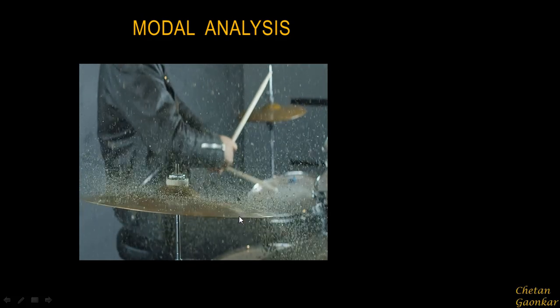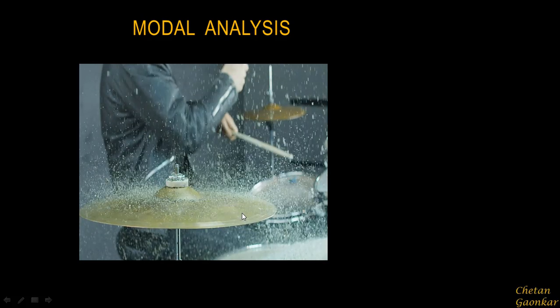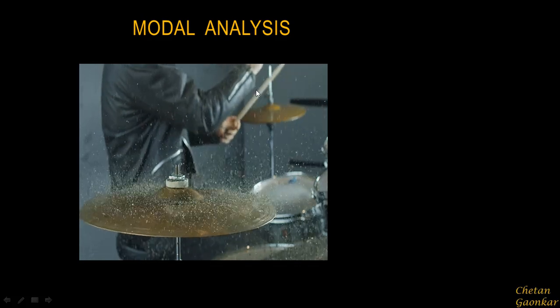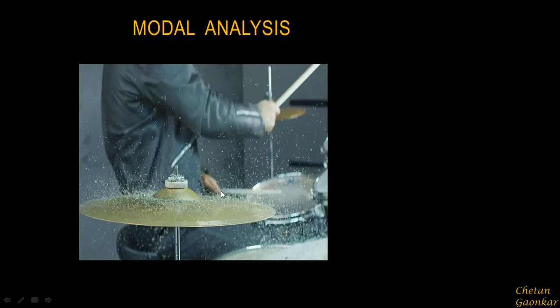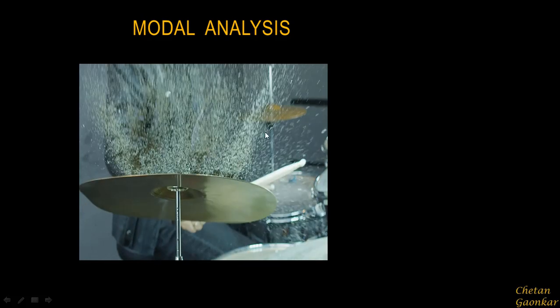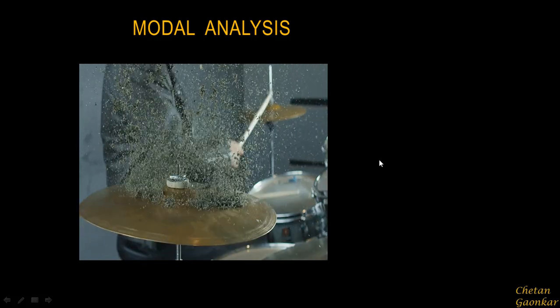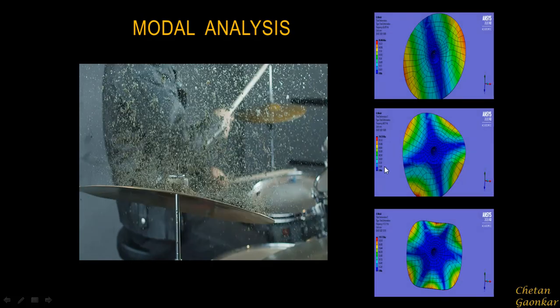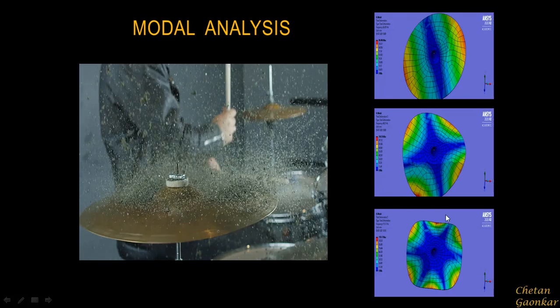Now basically the dynamic vibration behavior is nothing but, as we have discussed, the response of a structure under external excitation. Okay, so if somebody wants to understand the dynamic behavior of the structure for external excitation, we have to start again with performing the modal analysis. Once we do the modal analysis, we will be able to see how it behaves at different frequencies.